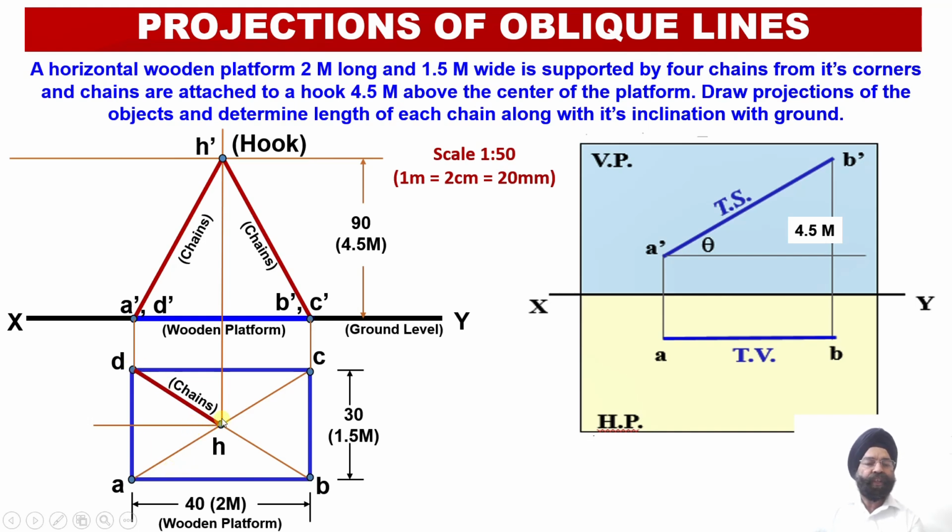the vertical plane. So what we are going to do over here, we have drawn a horizontal locus line through the point H so that we can rotate this line, that is apparent length projection HD, and make it parallel to the vertical plane.